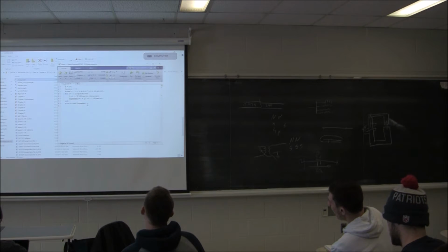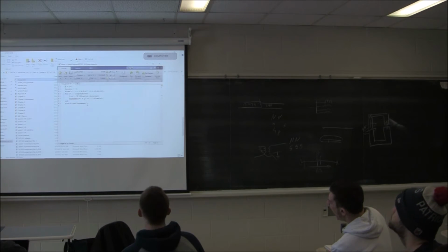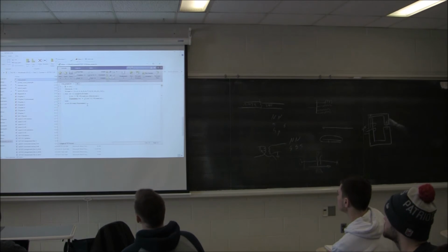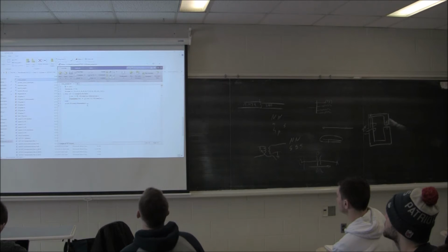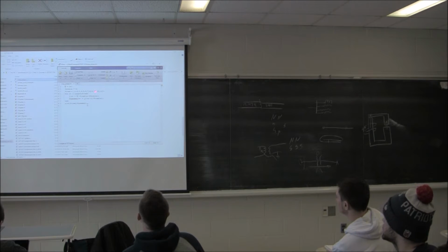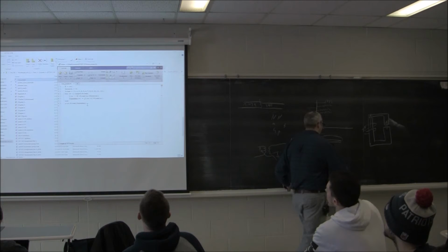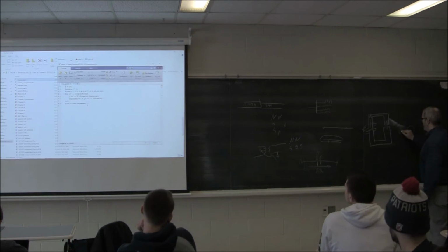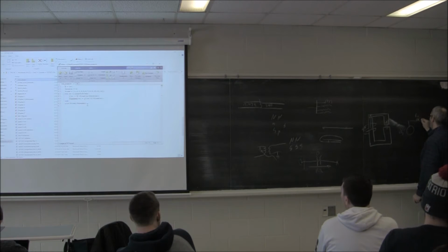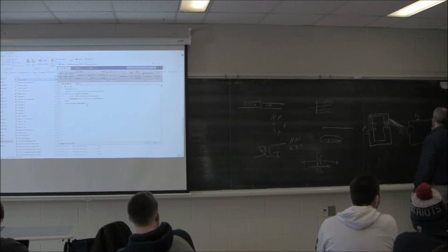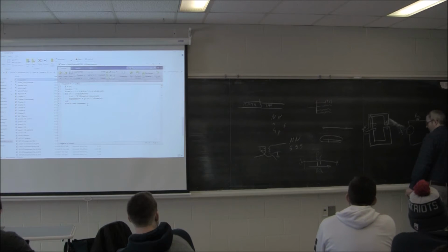Well, I'm going to just do a brute force approach. I've got a 24 volt source, and I've got an 8 ohm source impedance. And then I'm going to try a bunch of different load resistors. I'm going to go from 1 to 12 to figure out where max power transfer occurs. Okay? So I'm just going to do brute force. I'm basically going to say, take my voltage, divide by R load plus R source. So if I'm looking at my circuit schematic, here's my source, here's R source, and then external to that is our load. You do that all the time, right?